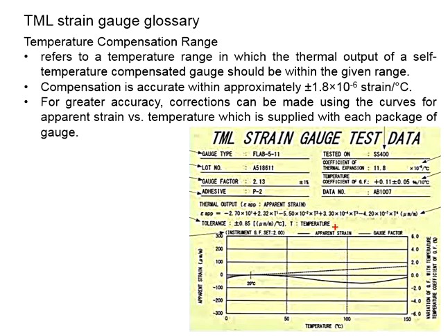Let's say now we are testing at 100 degrees Celsius. The variations will be about 1%. I believe that 1% shall be added to this gauge factor and the temperature coefficients of gauge factor. Correct me if I'm wrong.